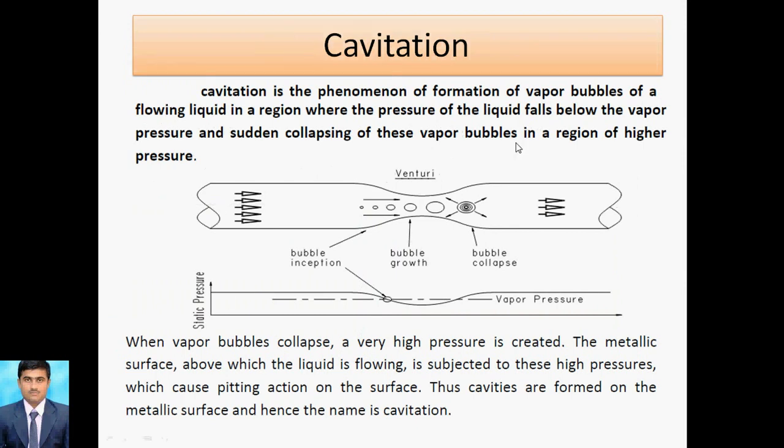Again I repeat, cavitation is the formation of vapor bubbles in a flowing fluid in the region where the pressure of the liquid falls. Where the pressure is less, the vapor bubbles form, and they collapse at higher pressure regions. That effect is nothing but cavitation.